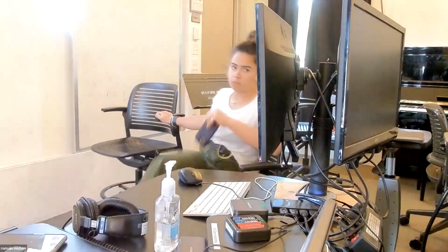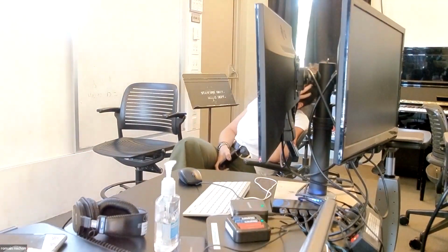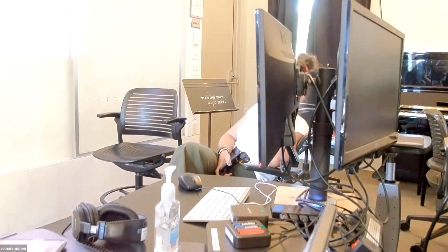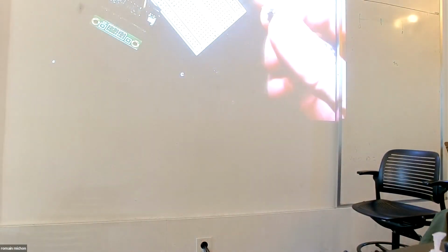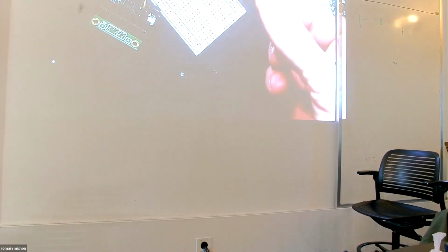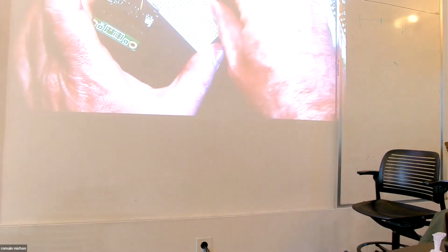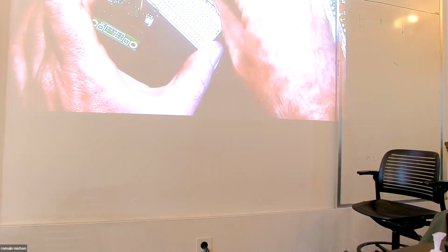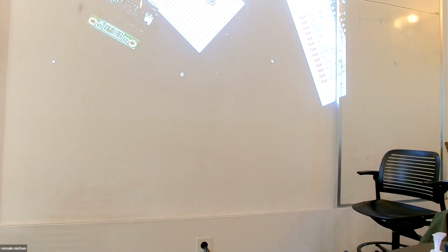Okay. So here I'm gonna add a button to the circuit. See that the buttons that we gave you, they have 2 pins. So I'm just gonna put it here like this. I'm gonna have to bring power to the button, and basically 2 pins is always the same circuit. It's always this. You need a pull-down resistor for a button.